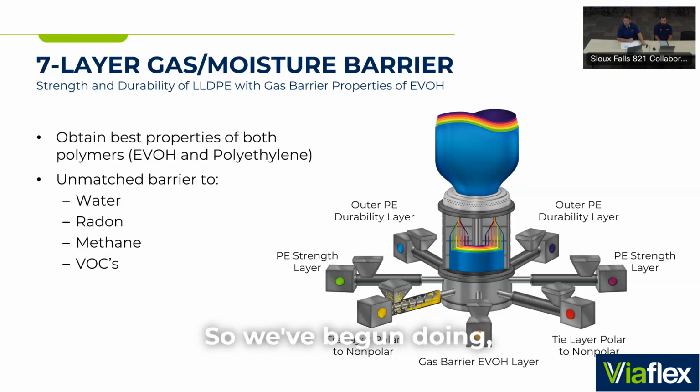We've also begun some early testing looking at the fluorinated compounds, the PFAS compounds. The data is early. We only have comparisons for co-extruded EVOH and linear low density, but even on those, you can see 1 to 1.5 orders of magnitude lower permeation coefficients. That's 10 to 15 times the protection for your structure and the occupants of those buildings from these types of compounds.